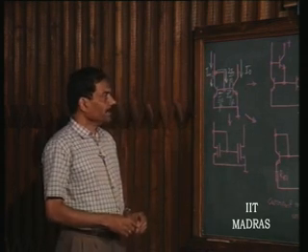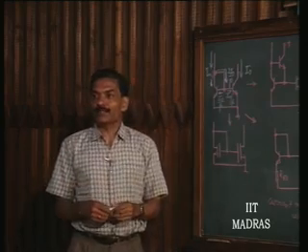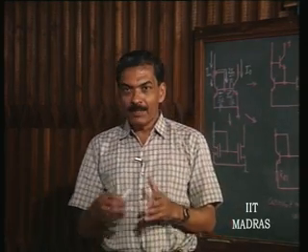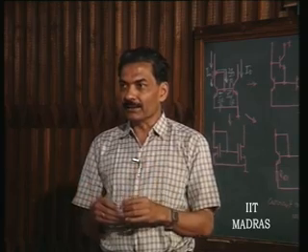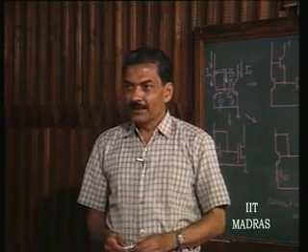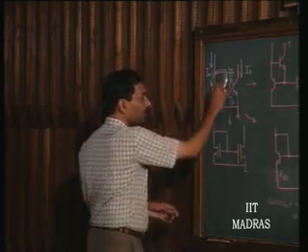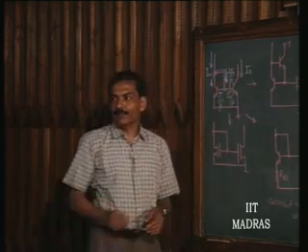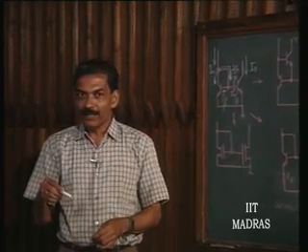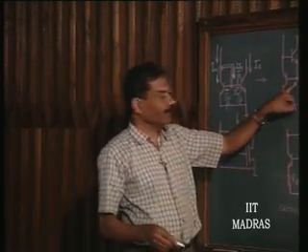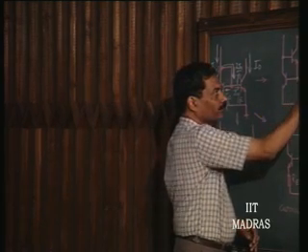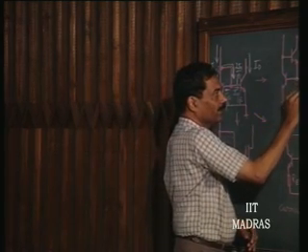In that attempt we can also adopt what is called a current amplifier. Why go for feedback and all that? We have abundant current amplifiers at our command. What is it? A current amplifier is nothing but the transistor itself. Instead of supplying this current directly from I reference, I would rather supply the base current of a current amplifier and make the emitter current supply the base currents of these two. So this is still equal to I naught, this is I naught by beta.